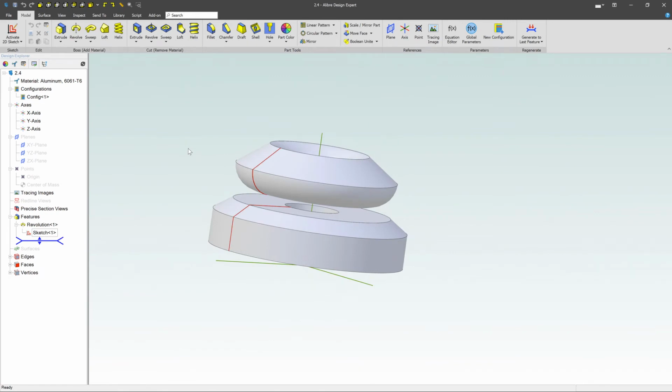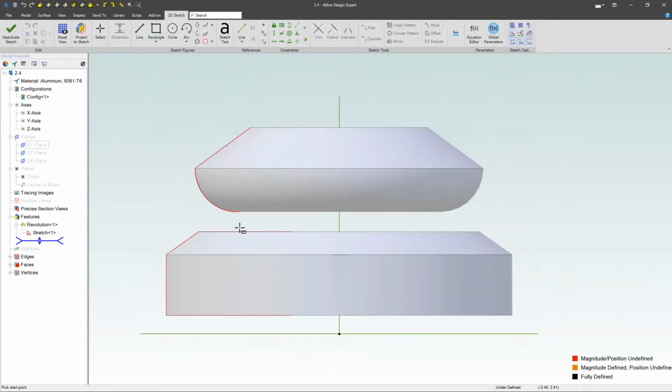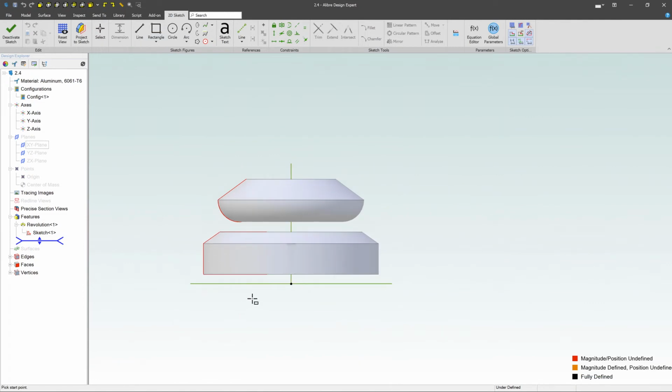So a bunch of things you can do with the revolve tool. But you can use squares, circles, polygons, whatever you want. Just have to have an axis of rotation and some basic shapes. Now, if I want to use the revolved cut feature, it works very similar, right? Now I've already drawn on that XY plane. Let's go ahead and create a new sketch there. And this time I'm going to create just a basic rectangle. But this time I'm going to create it right here. So I'm going to make a rectangle right there.